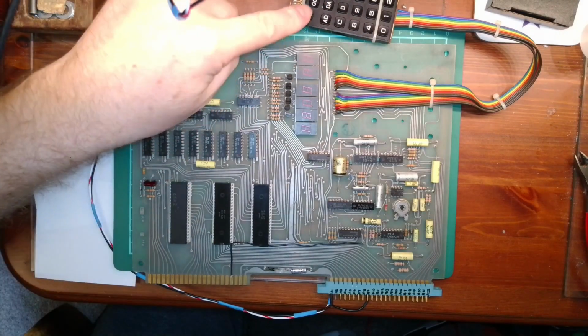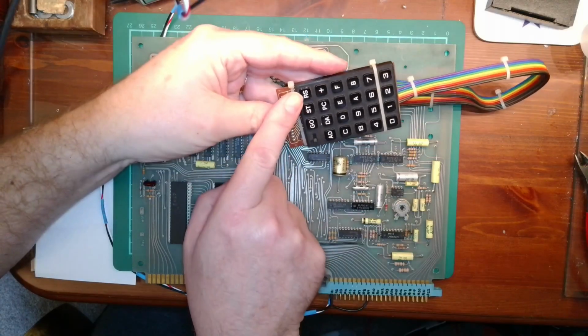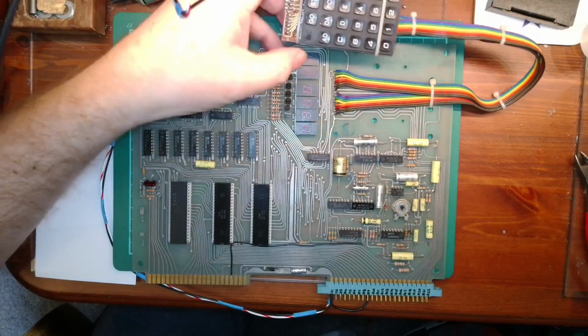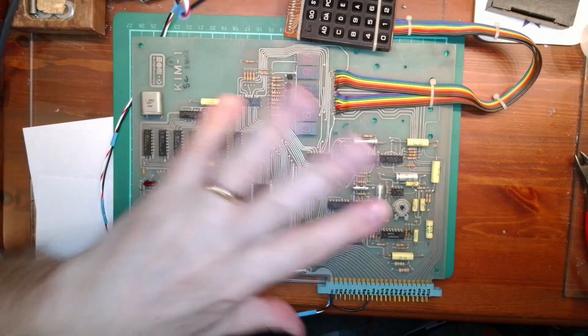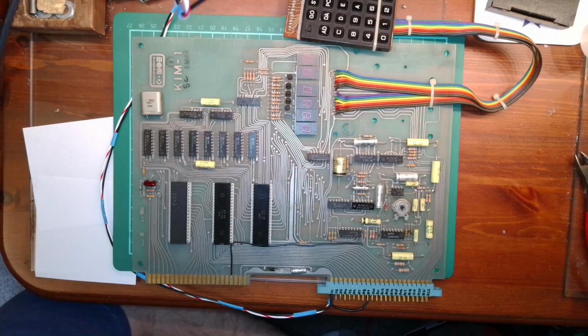I know the reset key works. I know this switch here works. And there's a few other glue logic chips in here, and we'll have to start it up and get it running. One thing I've done on this board is, when you've got a bare board, you have to have this link here. It connects the 0 volts to one of the decoder ICs.